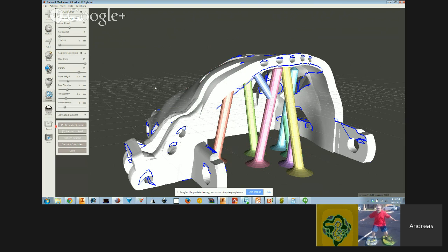If you're coming from a solid model, like let's say Fusion 360, I think it's all in millimeters when you export STL, so it'll come in as expected. But coming from other places, it's definitely something you want to check. Maybe just one time coming from that application, export a 1x1 cube, and go into Meshmixer, and you can check it in the analysis bucket.